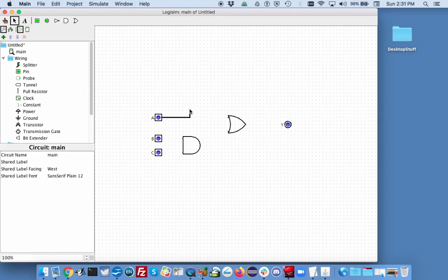Typically, we will need more than this, so we can simply drop the wire somewhere on the canvas. Then by clicking again on the end of the wire and dragging, we get another potentially bent wire segment connected to the original one. This allows us to route a wire from where it starts to where it ends. Notice the end of the wire will snap to the grid points on the canvas, making it easy to connect to the right place.